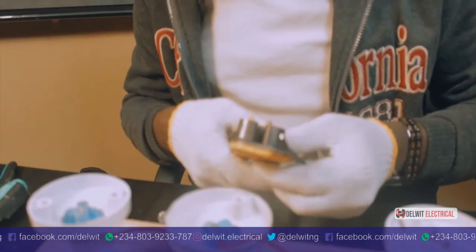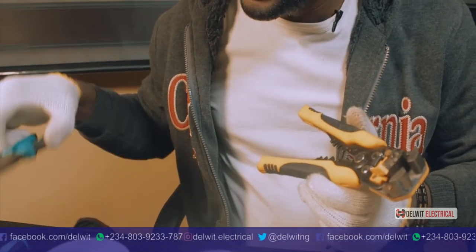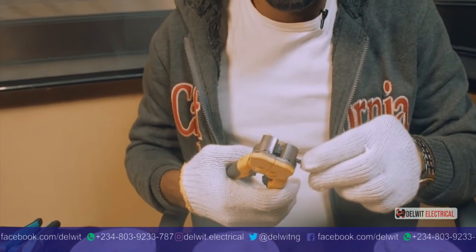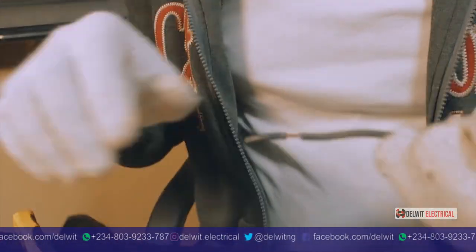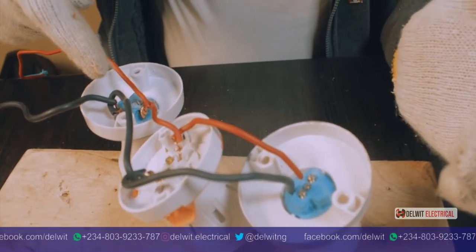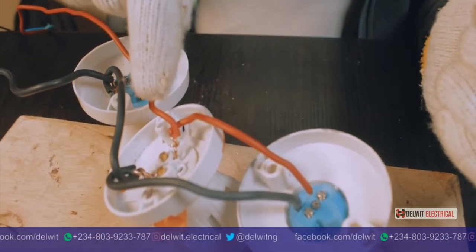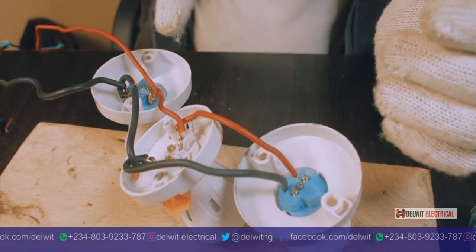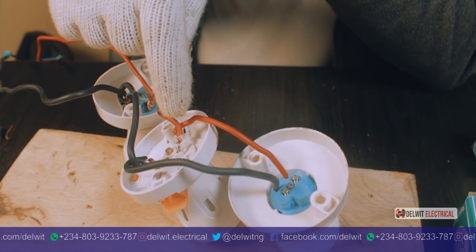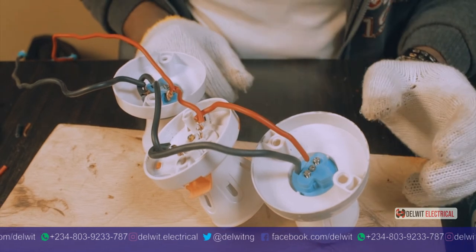All right. So now in this connection, we're going to be using a stripper. It's both a stripper and a cutter. We have a plier and we have our screwdriver. So the stripper is actually used to strip your cable. This is the parallel connection. You could see that the neutral is connected to this neutral, is connected down to this neutral. The live too is connected to this live, is connected to the live. So they have similar nodes. It's just the nodes are looped together. So the voltage at node A is the same as the voltage at node B is the same as the voltage at node C. So let's connect the bulb and see how the illumination will look like.